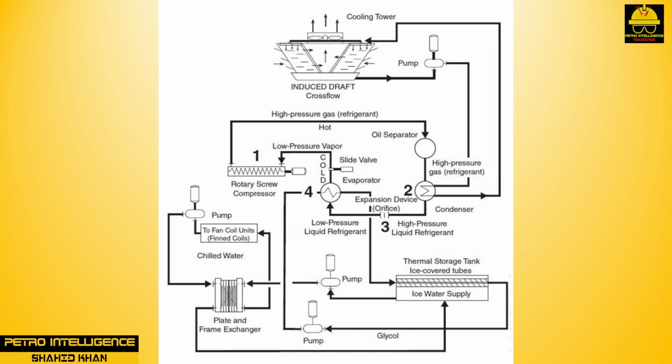Because heat is transferred from high-temperature areas to low-temperature areas, whenever it is necessary to cool a substance below ambient temperatures, it is necessary to artificially create a lower temperature first. To lower temperatures, process plants use fluids that boil at very low temperatures such as propylene, ethylene, or ammonia. That is, the same principle as the freon in your refrigerator, car, and house air conditioner.